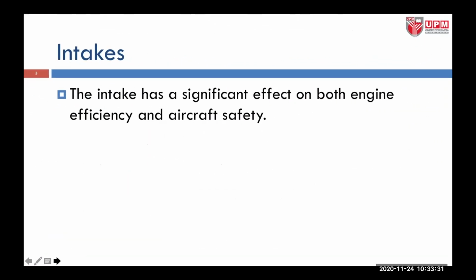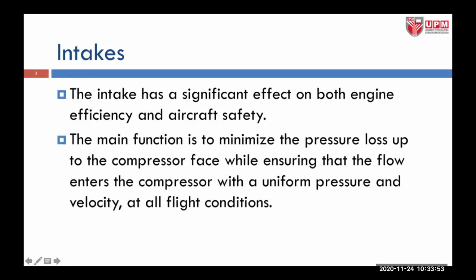Let us look into the intake. The intake has a significant effect on both the engine efficiency as well as the aircraft safety. You cannot just simply say that you can use any type of intake for any type of engine. It has a specific design for specific purposes. And the main function is basically to minimize the pressure loss up to the compressor phase.